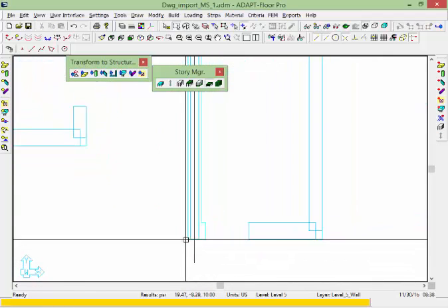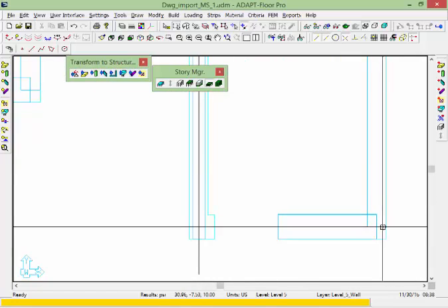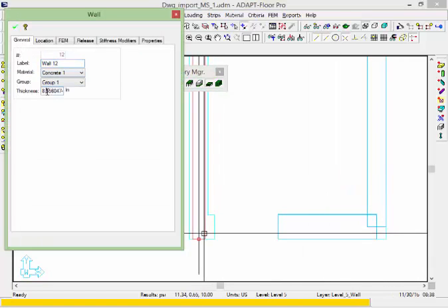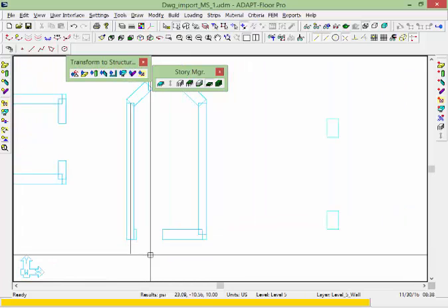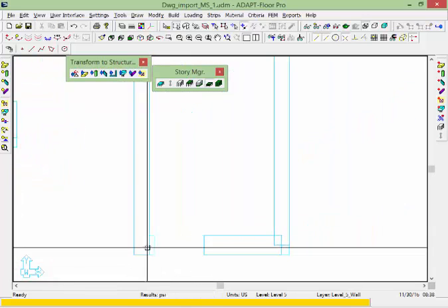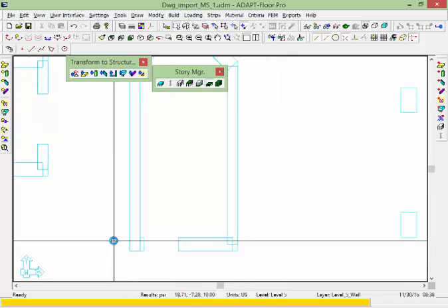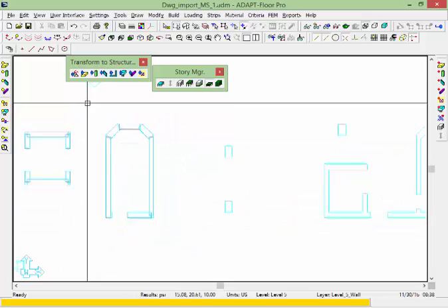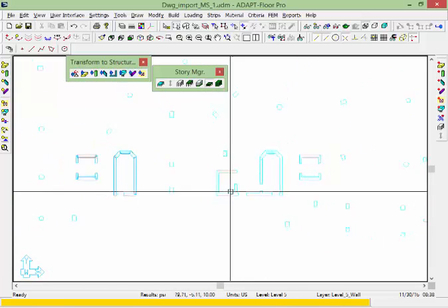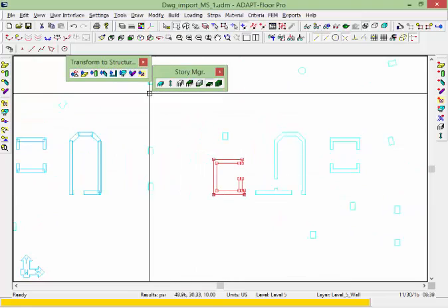The thickness of the wall, if we match the thickness of this side, it's 13.4 inches thick, it looks like. So we'll say 13.4. And we've done that. Now we could model this leg also if needed, but it has to meet a minimum threshold that's written in an initialization file in the program. So let's just go through and finish some of these walls.